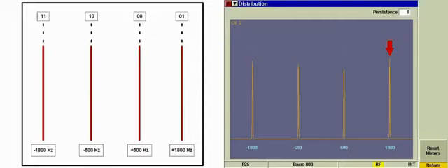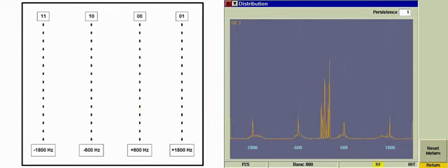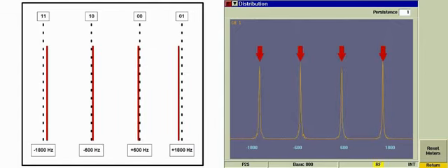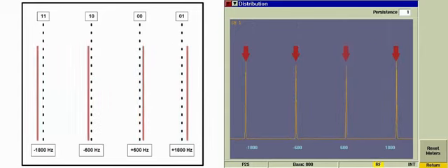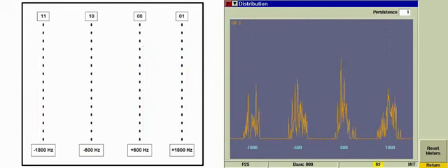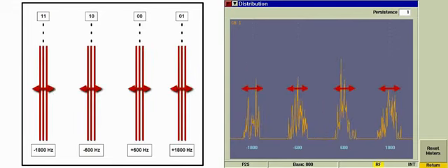The high peak at the plus 1800 Hz deviation point indicates that the signal is deviating more often to that point than, say, the plus 600 deviation point, which has a much lower peak. This signal is a standard 1011 pattern. Note that the signal deviates to the plus 600 Hz deviation far more often than to the other deviations. A signal with low symbol deviation will shift the peaks inward on the horizontal axis. A signal with high symbol deviation will spread the peaks outward. A signal with high RMS deviation error becomes obvious as the peaks spread out on the horizontal axis.